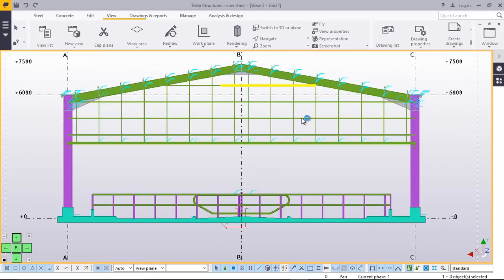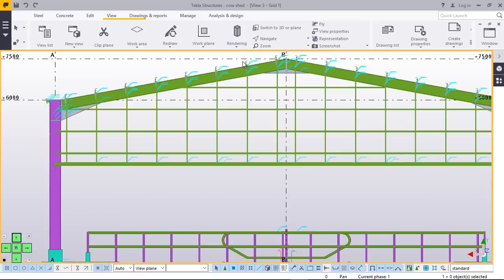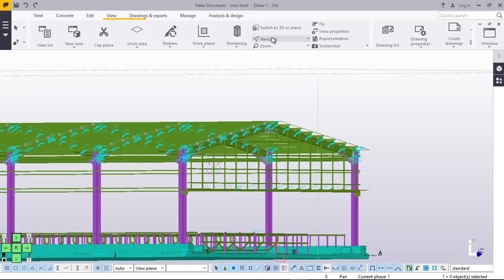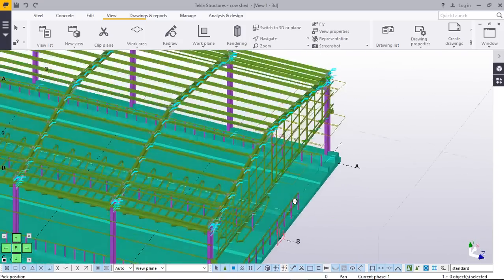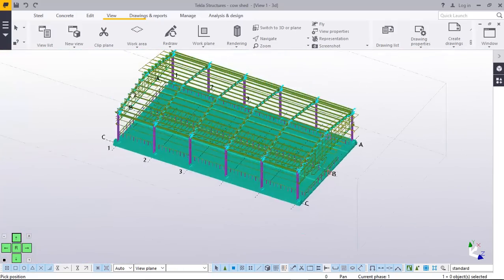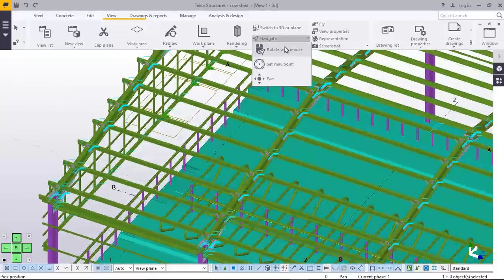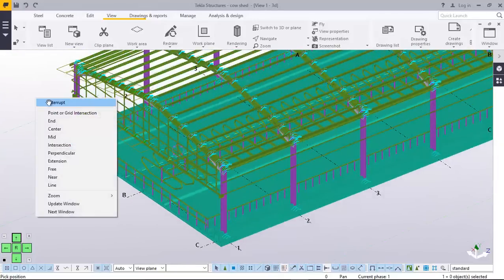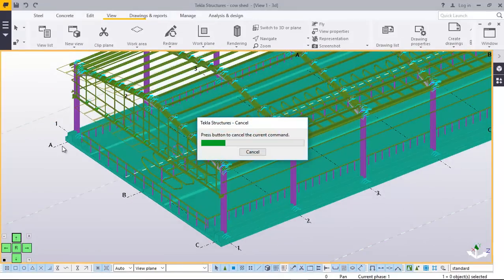Now on the next presentation, we'll place the sheets on top here, well trimmed, with a well trimmed side clad on the gable side, this side and on the other side. If we switch back to our isometric view, we'll place cladding here and a cladding on this end. On this end, I'll right click and redraw this.